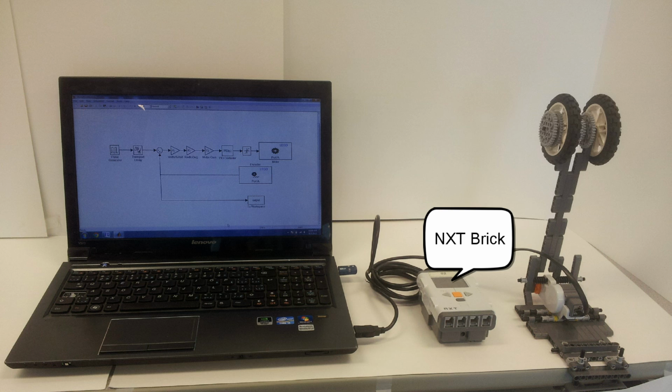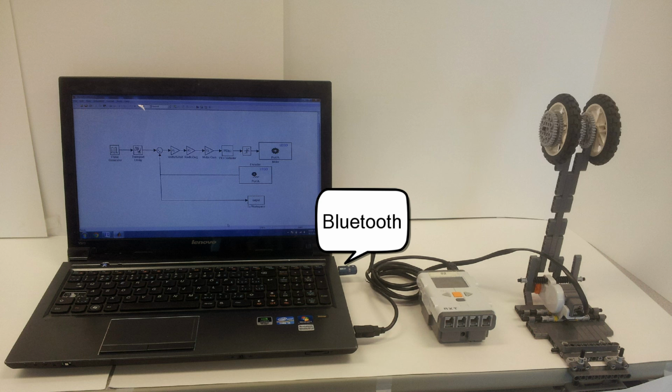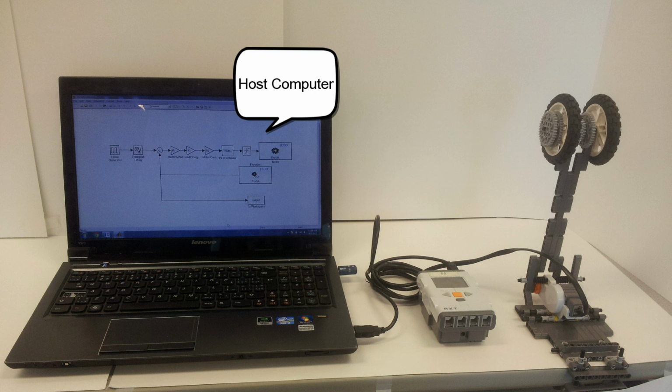The NXT brick powers the system, as well as controls it. Connecting the NXT brick to the host computer is the USB cable, which has the purpose of uploading the Simulink model to the NXT brick. To sample and record the encoder data onto the host computer, a Bluetooth connection is used. The host computer is used to design the Simulink model as well as interpret the encoder data on Matlab.